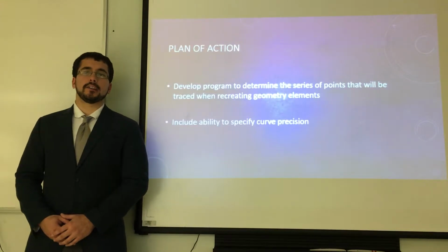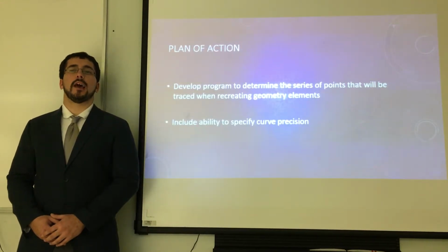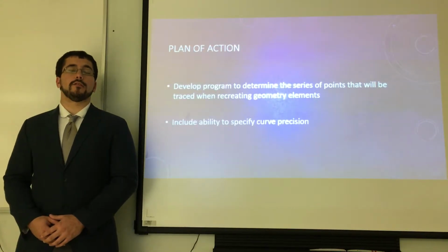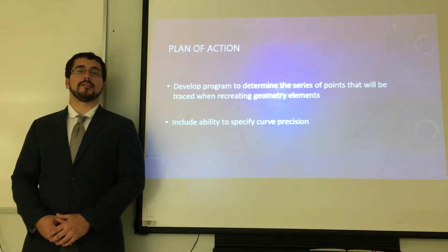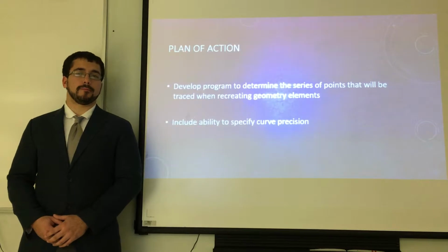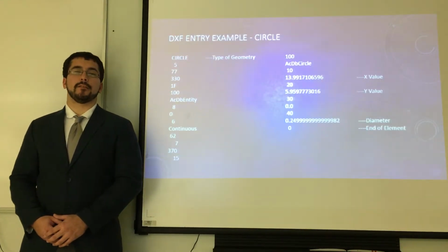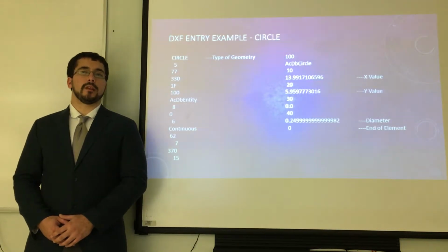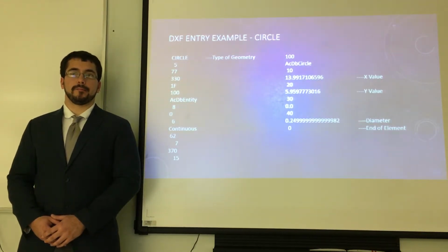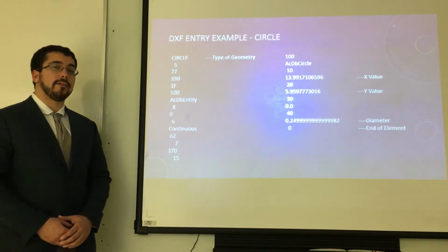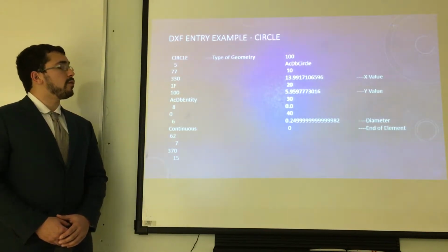To accomplish the task of translating lines and curves held within DXF files, I will develop a program using LabVIEW to determine a series of points to trace between. Sketch geometry is held within a DXF as an identifier followed by key information. This is an example of an entry within a DXF file. This is for a circle.